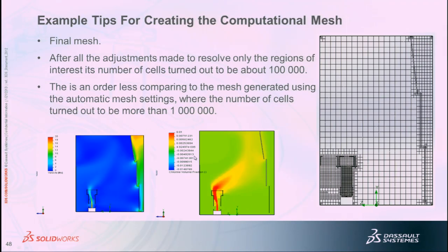And this is actually a mass fraction plot of chlorine, actually volume fraction of chlorine. And again, it's being suctioned. There's actually a little bit of vortex flow that's going in there that was very interesting to the customer, and they were able to make some decisions on how they wanted to improve this hood design that they were looking at.